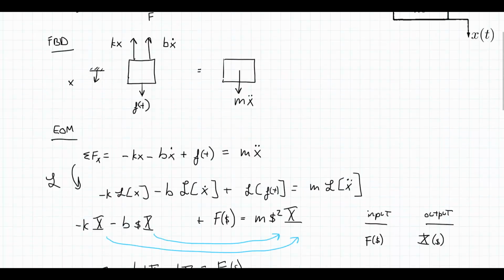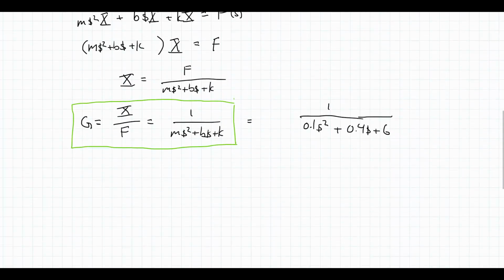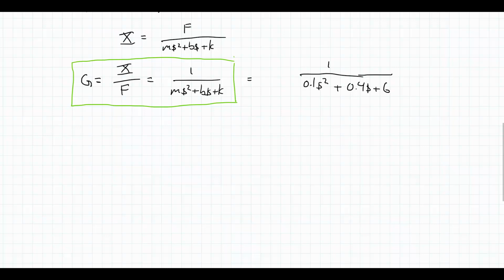Well, we're going to do this numerically using the transfer function tool and the step function in MATLAB. But what we can do before we get there is at least know what happens at time 0 and at steady state as time goes to infinity using the IVT, the FVT, the initial value theorem, the final value theorem. So we can do more of this by hand before we get to the numeric output from MATLAB.